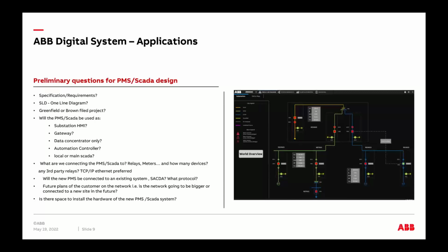What I mean by that is maybe there is an existing SCADA system that they already have, and they want your system to act as, for example, a mini SCADA to their system. So they're pulling data from your system, and you give them that signal. All those signals go into their system through, for example, OPC UA, like I mentioned earlier, or some type of connection that you do for them.